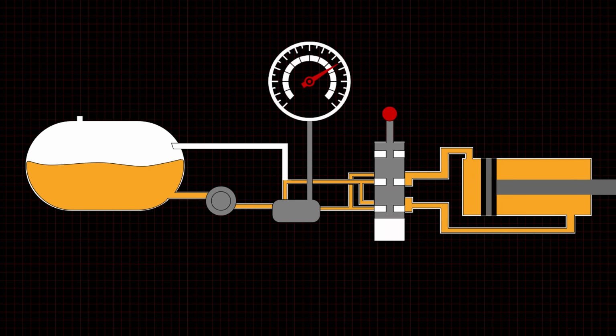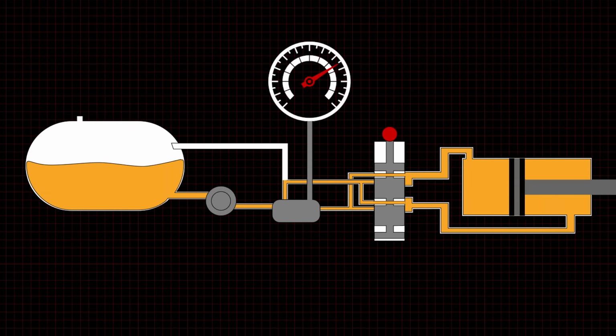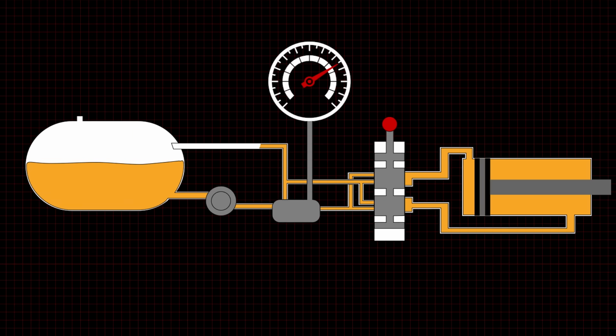When the valve changes position, the actuator moves proportionally to the volume of fluid pumped. The pressure required for motion is equal to the applied load. In return mode, the expelled fluid returns to the reservoir to be used again. In the valve center position, the actuator cannot move due to changes in load because the fluid is not compressible or expandable. This is how hydraulic actuators are infinitely positionable.